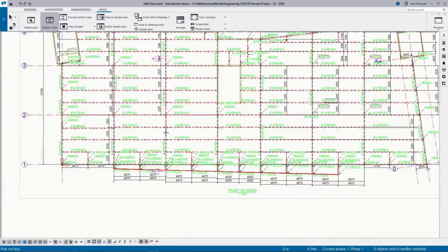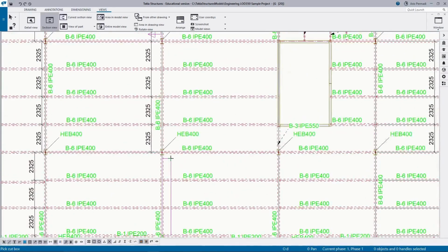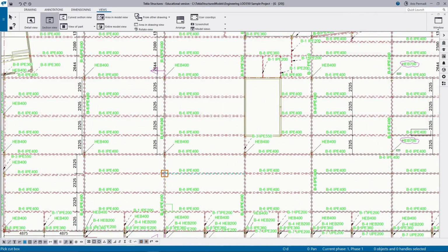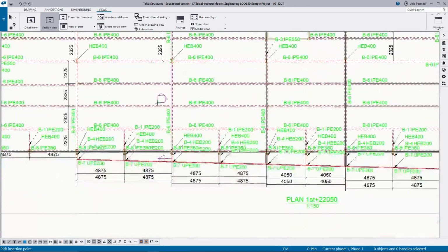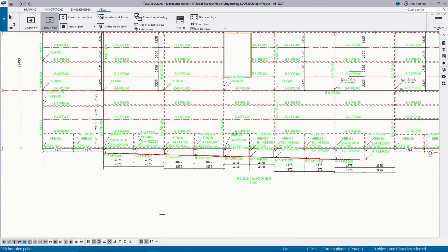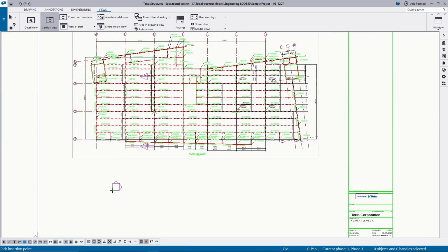This shows how much length, how much boundary you want to put. I can choose to not fully have the cross section here. I will just place it here and then until here, to see it has the column. Okay, after that this symbol is where you want to put the cross section view. For example, I will just put it here.